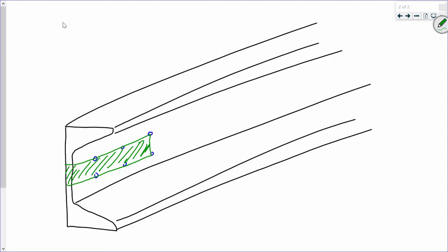So does that make sense? Now let's be clear. Shear lag factors are trying to account for stress discontinuities. I'm not saying there aren't going to be stress discontinuities in an I-beam with bolts through the flanges and the web. Of course there are. But because the load is directly being transmitted to all of those elements, while we get stress discontinuities, we can essentially count on all of that net area being effective to resist that load. So that's why we take a U value to be 1 if we had the situation that you're talking about. Does that make sense? That answer your question as well?